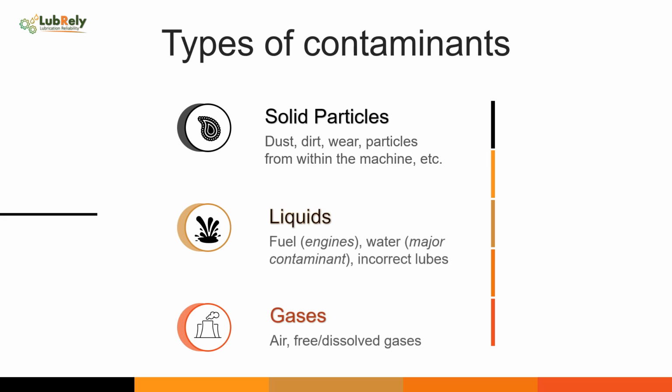Liquids, such as fuel, water and even from incorrect lubes. Meaning when you add the wrong oil, with for instance the wrong viscosity, then that becomes a contaminant. Water is one of the most common contaminants. They can occur because of washdowns, condensation, poorly sealed reservoirs. Water increases the wear rate, and thus reduces bearing life.